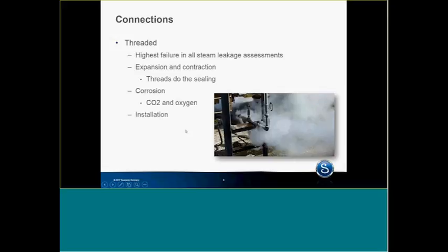Connections. Threaded pipe. Every time I do a steam leakage assessment, number one, threaded connections. Bar none, threaded connections. People always ask me, how do I get around having steam leaks? Don't thread pipe, period.